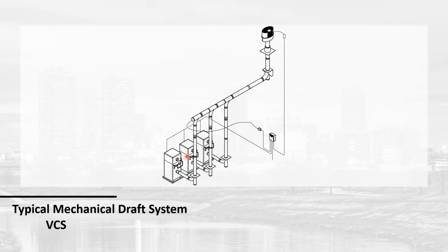And so by doing that, they pump a whole bunch of ambient air through the chamber and up the stack. Obviously, all of that air is going to come up here and be sensed by that sensor. We're going to see a change in pressure, and we're going to ramp our fans up. Once pre-purge is complete, our fan ramps up, the boiler fan ramps all the way down and goes to ignition. Obviously, when we change volume, temperature, etc., that pressure is going to change, and we'll modulate that fan back down accordingly.